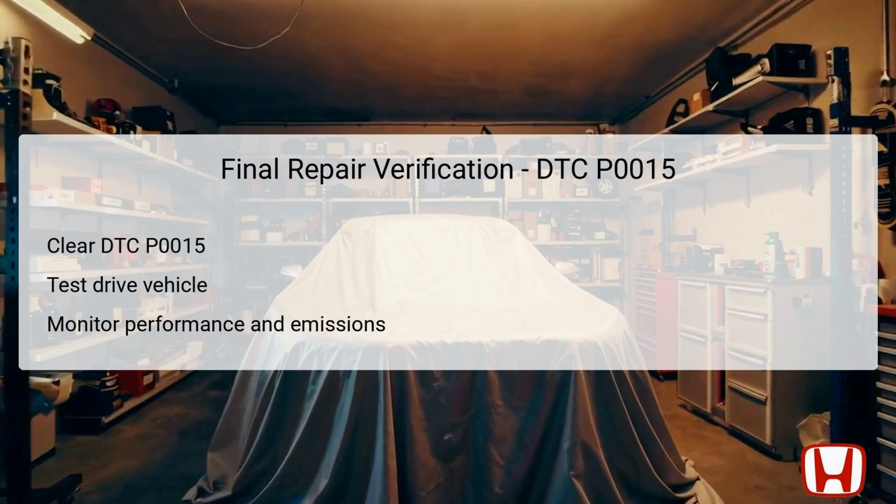After completing all troubleshooting steps and making necessary repairs, it is crucial to verify that the system is functioning correctly. Begin this process by clearing the DTC P0015 from the vehicle's computer using an OBD2 scanner. Once the code is cleared, conduct a test drive under various operating conditions to monitor the vehicle's performance closely. This drive should include acceleration, slow speeds, and possibly uphill climbs to ensure that the VTC system operates as intended.